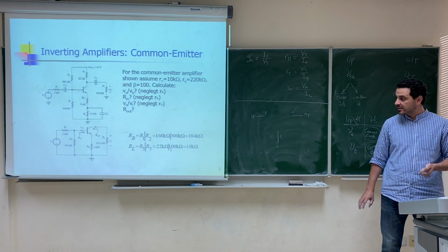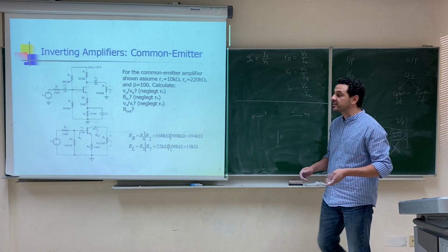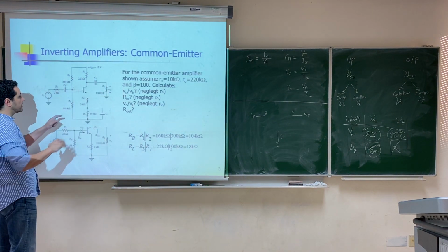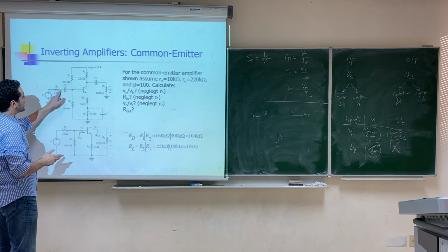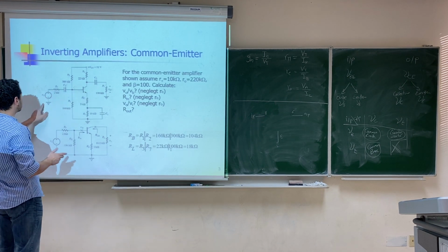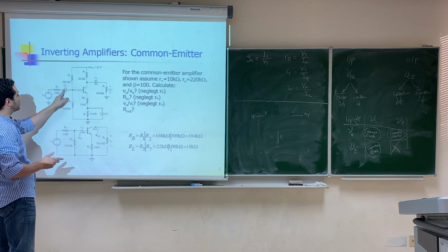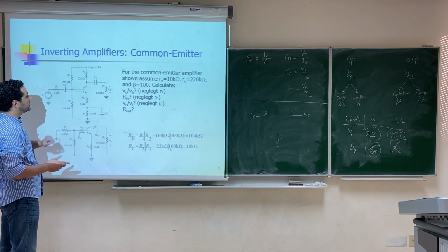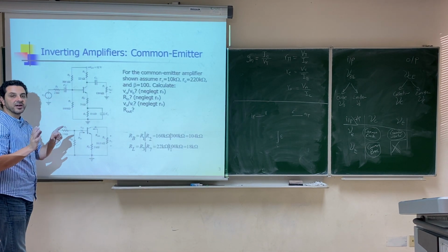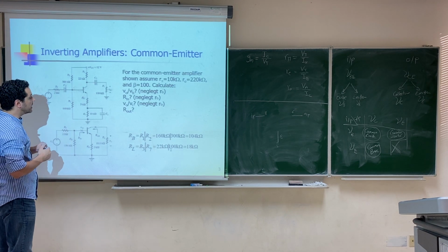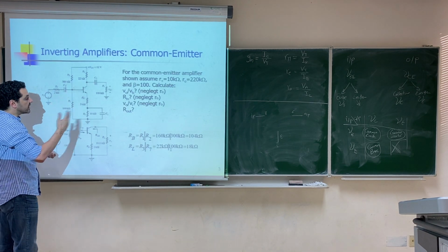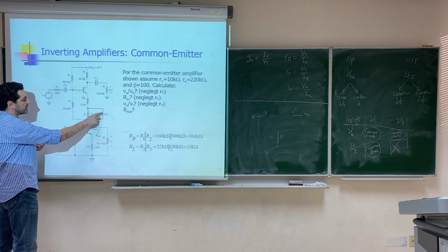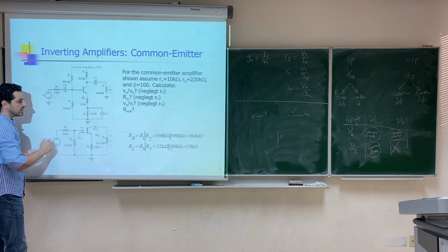In any amplifier circuit, before we end this video, we will notice that we have some capacitors. These capacitors can be classified into 2 types. This is an example of an amplifier circuit. We have some capacitors that we put before the input and the output. So this is our input. We usually connect it to the amplifier through a capacitor. Also the output is usually connected to the amplifier through a capacitor. These capacitors are classified as coupling capacitors. While there is another type of capacitors that will appear sometimes in our circuits, like this capacitor, which will be connected parallel to some resistors. This is called bypass capacitors.